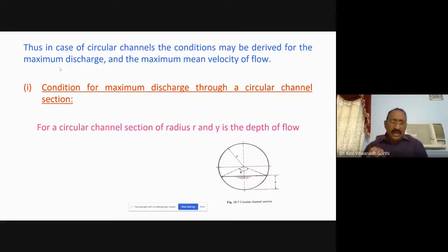So here I would like to draw your attention once again, referring to our pipe flows. When you take a pipe flow, you must have observed different velocities, like the local velocity at a particular point. Then the maximum velocity would be, obviously for the pipe flow, at the center. Towards the boundary, the velocity becomes reduced, and exactly at the boundary, the velocity becomes 0 following the no slip condition. This is what we have learned in our pipe flows.